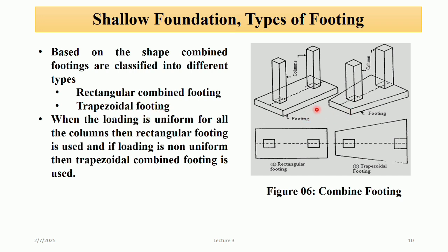Now you will be thinking about where we have to provide rectangular footing and where trapezoidal footing. Based on the load: when the load is uniform on the columns, you provide rectangular footing. When the load is non-uniform, you provide trapezoidal footing.